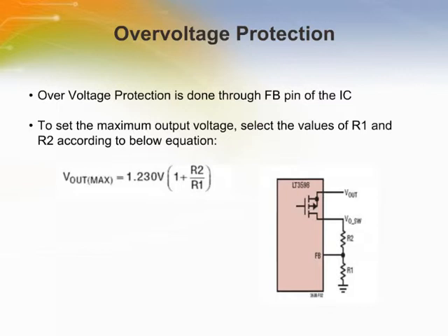Under normal operation, LED 1 to LED 6 pin voltages are monitored to provide feedback information to the converter for the output voltage regulation given the programmed LED current. The maximum output regulation loop is activated only when all LEDs are open.